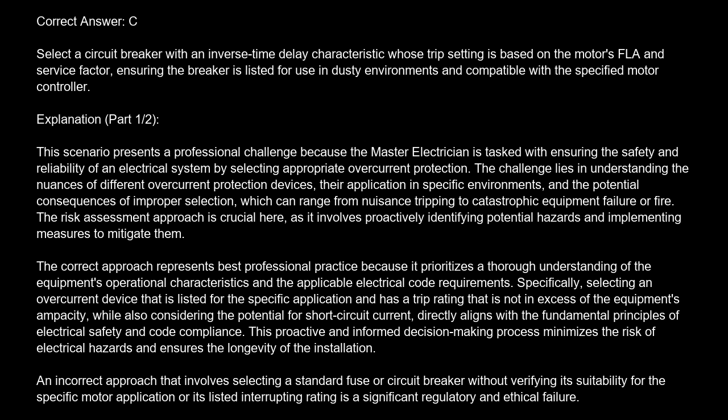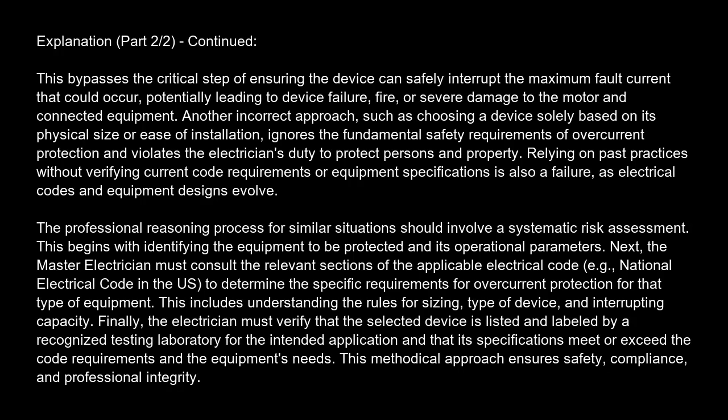An incorrect approach that involves selecting a standard fuse or circuit breaker without verifying its suitability for the specific motor application or its listed interrupting rating is a significant regulatory and ethical failure. This bypasses the critical step of ensuring the device can safely interrupt the maximum fault current that could occur, potentially leading to device failure, fire, or severe damage to the motor and connected equipment.